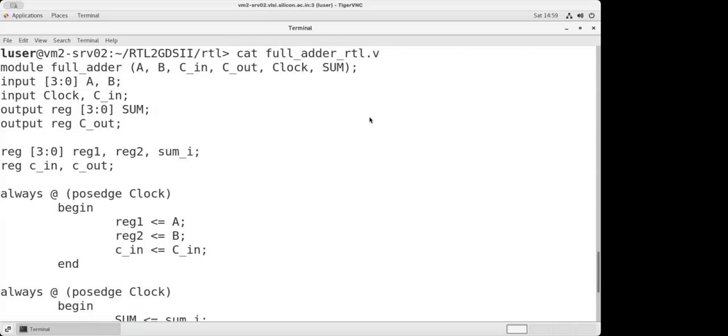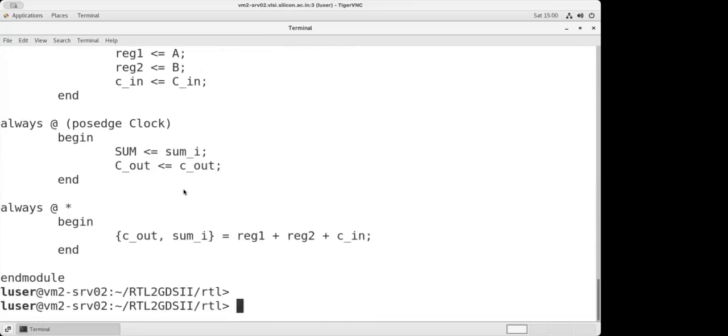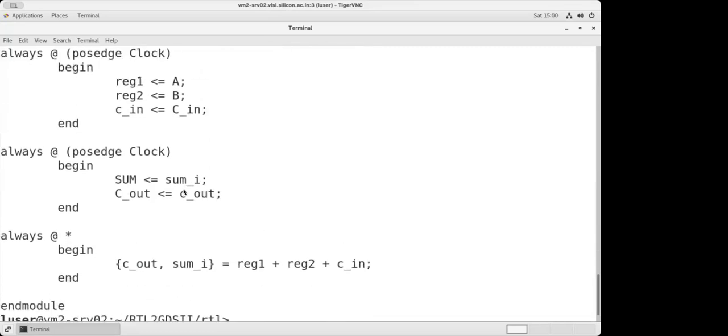Now the same thing you can do on the output side also. You can say, on the output side also I will have 4 flip-flops and the clock will be the same, and the output will come at any point of time. Make sense, guys? That's the reason the clock is a part of this particular program. Now, if you see here, in Verilog, if you need a sequential part and you want to trigger it at a particular edge, there is an always posedge.